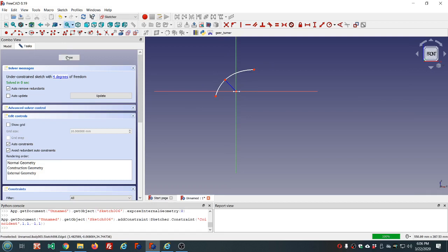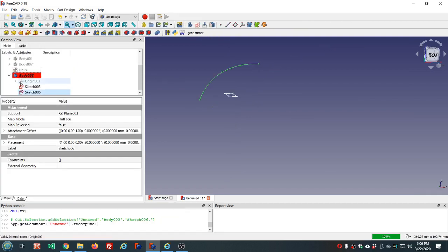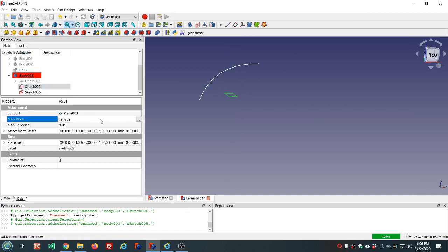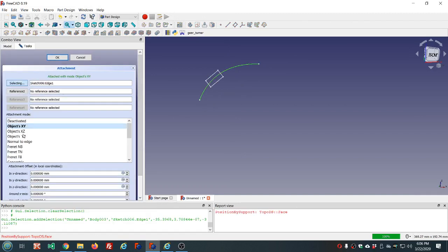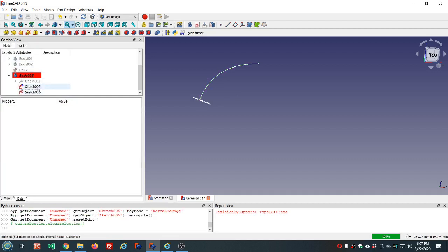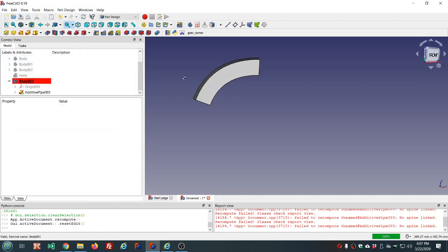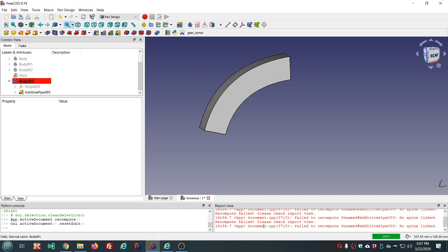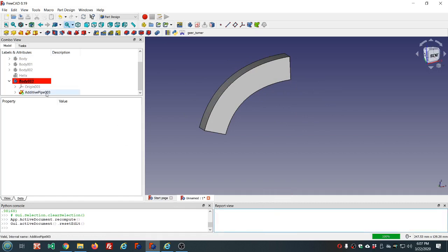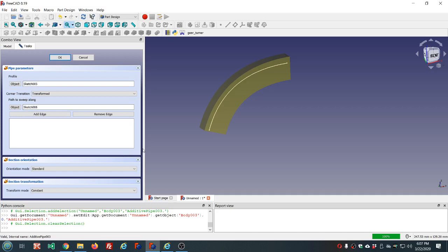So we have an arc of ellipse. So now we've swept our profile along the arc of ellipse. And we have some options down here. Well, we didn't look at these options yet. Auxiliary and binormal.